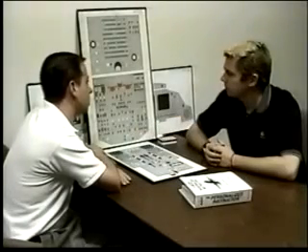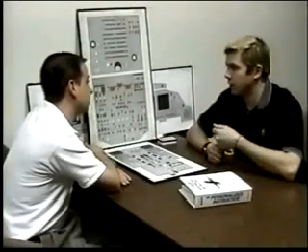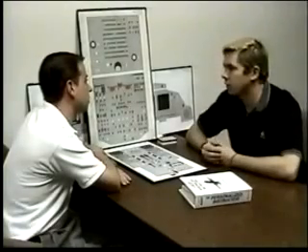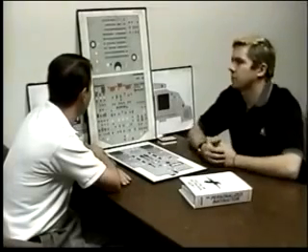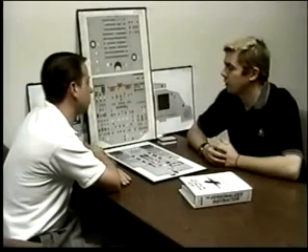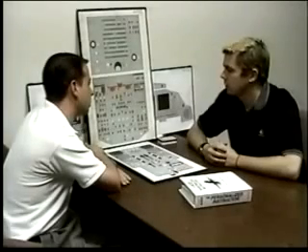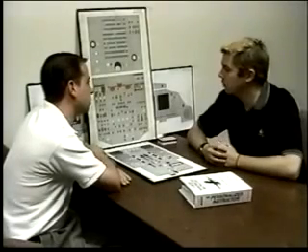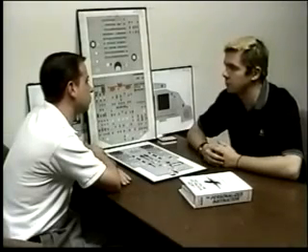When will you lose the emergency generator on the 319 and 320? Well, on 320, it's gear down. On a 319, it's when you get below 125 knots. Okay, that's occurred. We're back to battery power, and you land, and you get below 100 knots. Below 100 knots, the battery's connected to the DC battery bus. What occurs at 50 knots? Below 50 knots, you lose AC essential bus, and therefore you lose all the displays. You still have the ability to communicate through the AC essential.